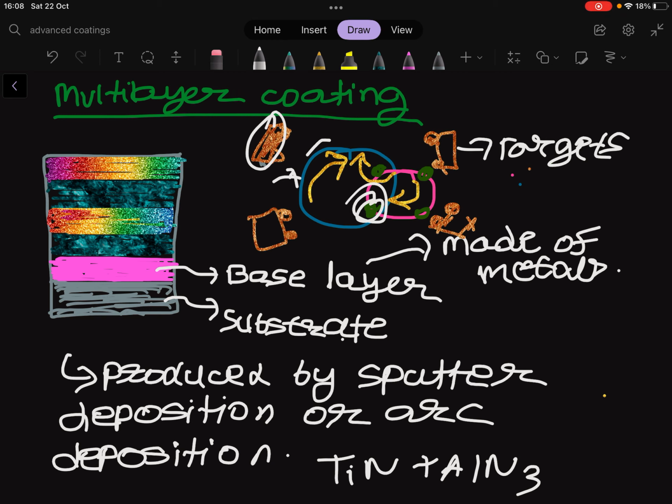Through the multi-component coating structure, we observe much less chance of crack propagation from the top layer to the substrate interface. Most probably the crack is stopped by these intermediate layers. So the result is low wear rate and high wear resistance. So aluminum titanium nitride or titanium nitride multilayers significantly increase the lifetime of the cutting tools used in machining operations.